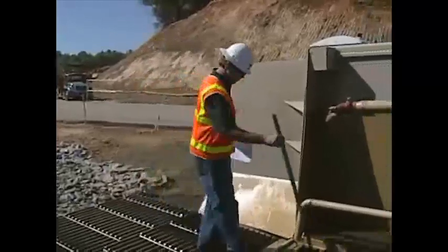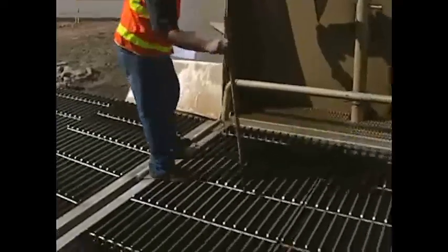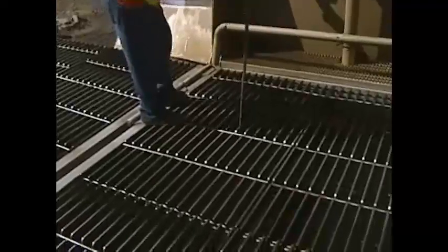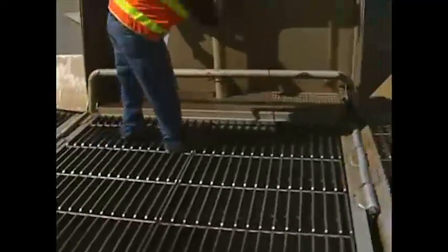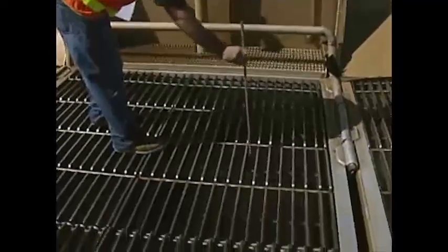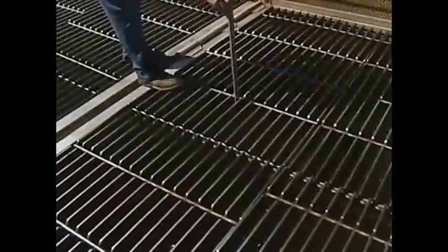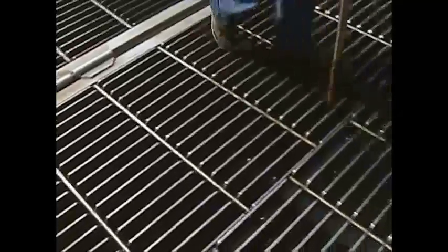Inspect the sediment control device and ensure that accumulated sediment is removed when the trap storage capacity is 1/3 full. If a sediment control device was not incorporated into the design, make a note on the inspection form, follow up with the contractor, and request an immediate corrective action. If the resident engineer approved the installation of a prefabricated steel plate, check to see if mud has accumulated and needs to be removed.